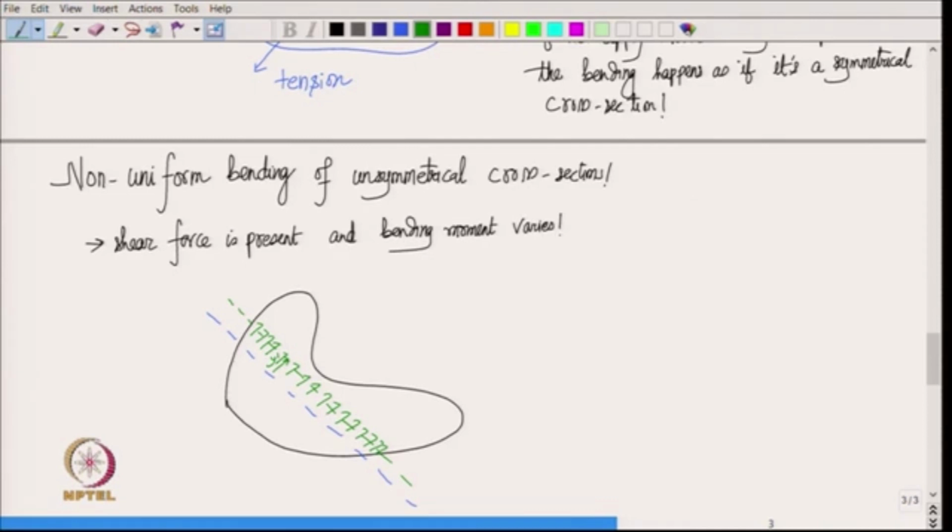So, remember in the last class we were working out the circular cross section, and there also we could not really say that the shear stress would be uniform along this line. And what was the reason? That was because if we take it uniform, then the shear stress will have a component in the radial direction, which violates the free surface condition.